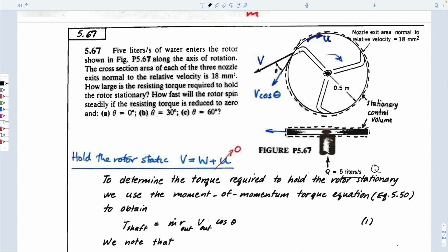And of course that water gets divided up into 3 equal portions, which would be that 1.66 liters comes out of each of these because of continuity. And it then comes out of the jet, and we could calculate, if we had an angle on this that's theta degrees, then we have to do the calculations relative to the tangent, relative to this velocity